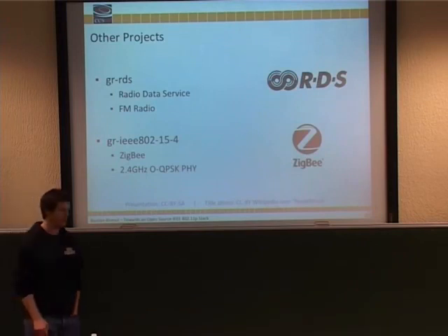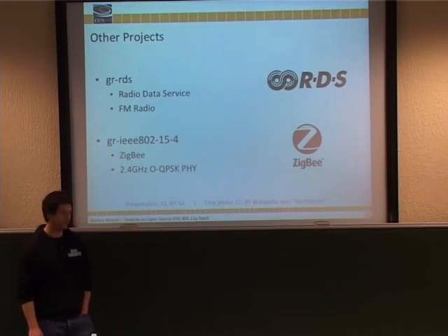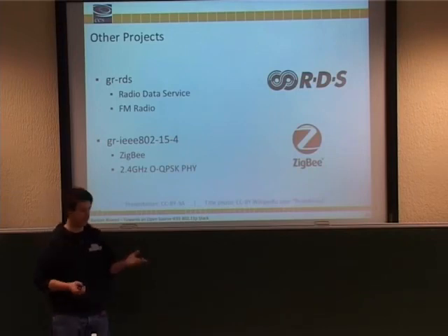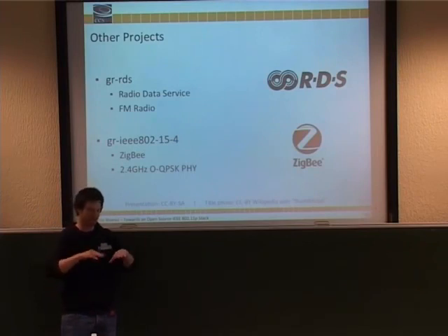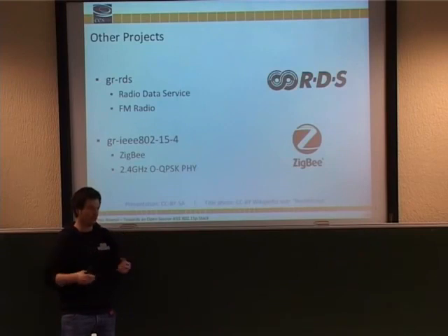Yes? Probably you are aware of the WAVE, the DSRC project. It's good that they finally standardized the physical layer, but is there some standard coming out for the link layer as well? So there's ETSI ITS-G5, and then there is this DSRC WAVE, and they both use 11p as the physical and MAC layer on top of that. And both give recommendations on how to use this physical and MAC layer. So there's no definite answer to that.